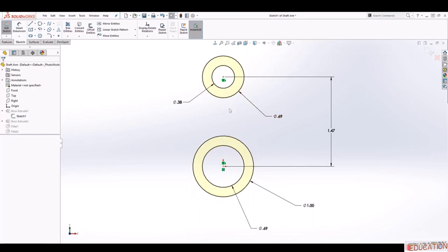Let's say you've modeled your part. I've made this part now, and let's say I decide that, oh, this dimension is different now and I just want to change it. So what parametric means is the dimensions and the relations allow us to go back into the sketch we've already made and easily change it, and it will be automatically applied to our part. So I'll just show you.